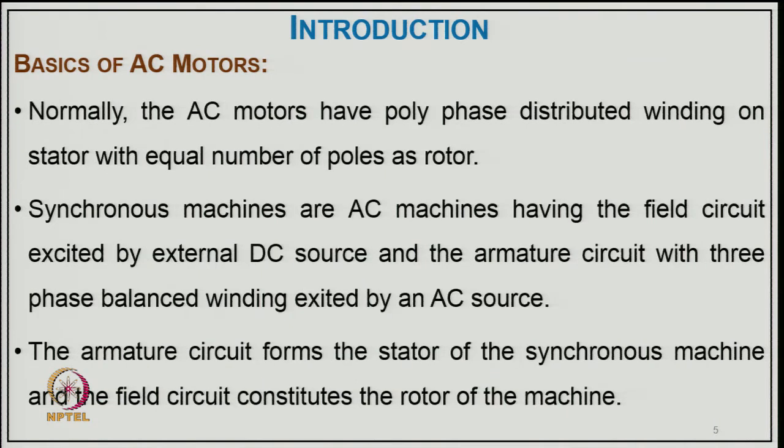So, normally the AC motors have polyphase distributed winding on the stator with an equal number of poles on the rotor. Synchronous machines are AC machines having the field circuit excited by an external DC source and the armature circuit with 3-phase balanced windings excited by an AC source. The armature circuit forms the stator of the synchronous machine and the field circuit constitutes the rotor of the machine.